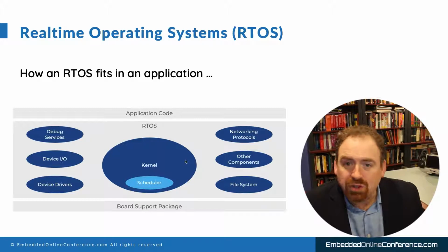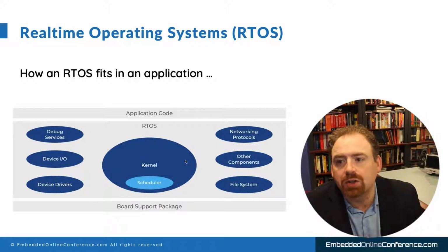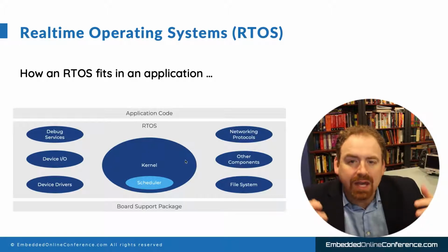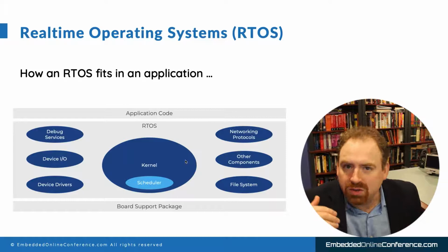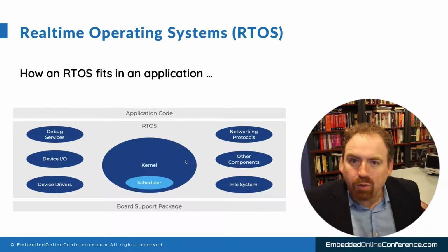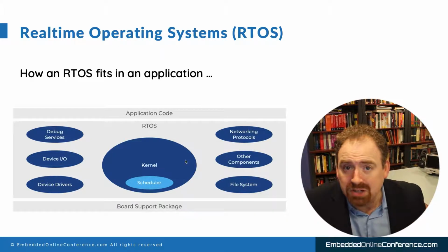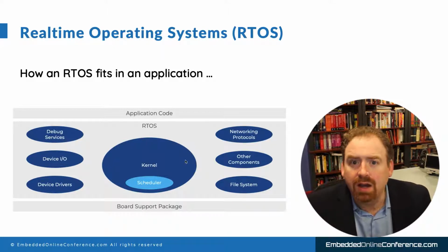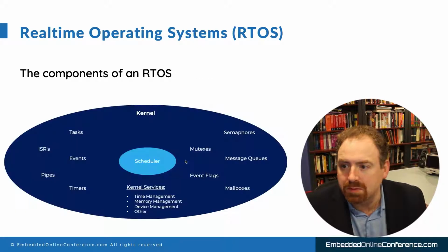So once you have that core, you can look at an RTOS almost as a middleware piece to some degree. All the application and the high-level middleware then runs on top of that RTOS, and you design your application on top of it. So at least that's where an RTOS fits in. And like I said, it can really help you reduce the complexity of your application and not have to worry as much about the complex timing and some of the determinism issues that often crop up that you have to fight with and struggle with when you're working with bare metal systems.